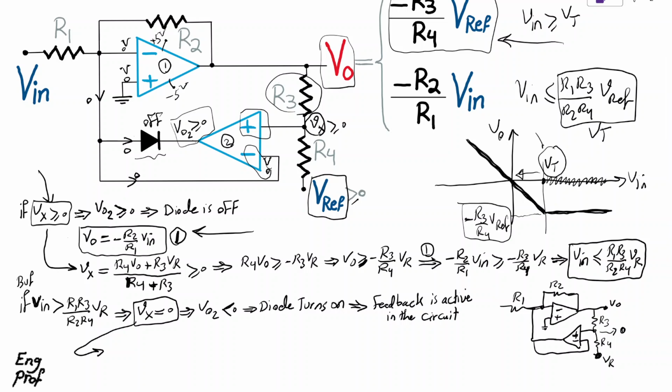So in this case, we would write a KCL at the Vx node. Since no current can go in or come out of the ideal op-amp's input terminals, since IP and IN, the currents through the positive and negative input terminals, are 0, writing a KCL indicates that the current that flows from Vout through R3 should continue flowing through R4 toward Vref.